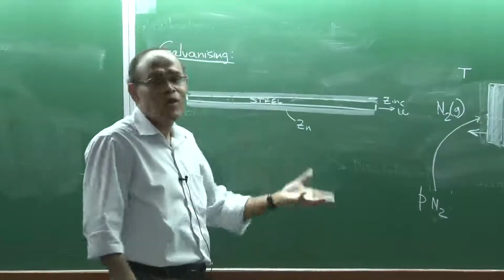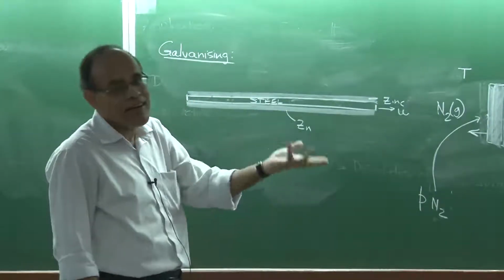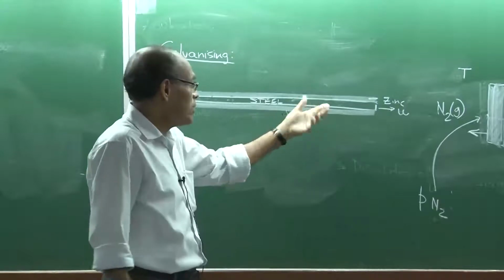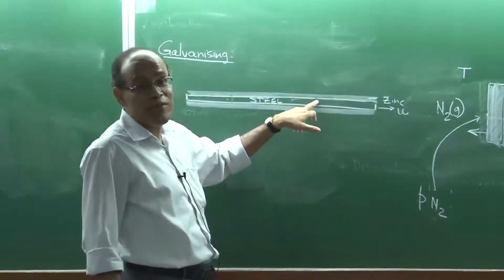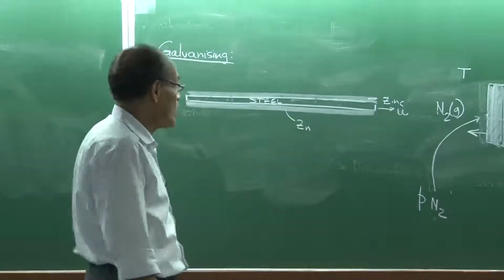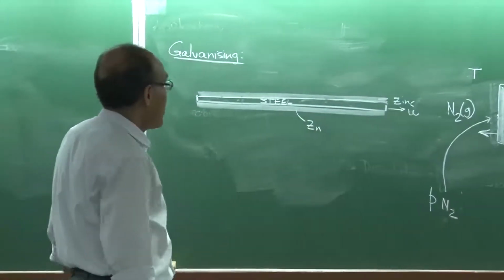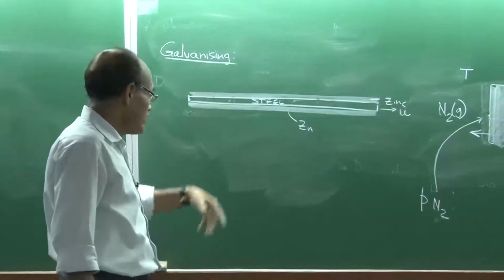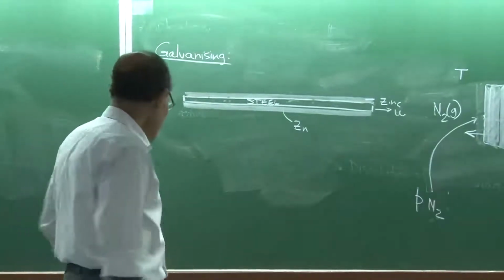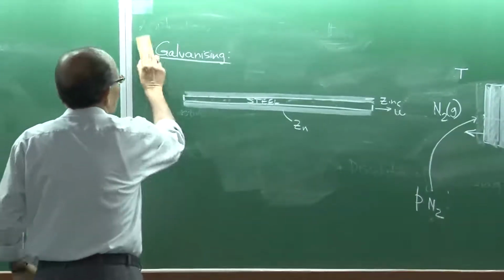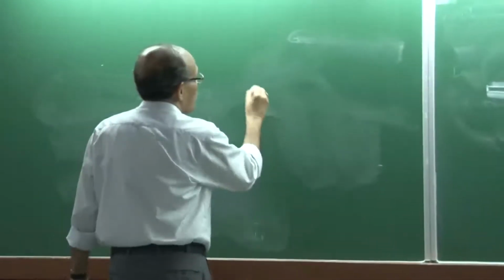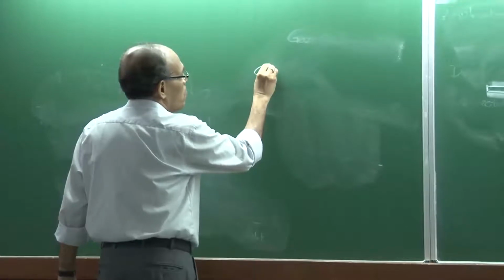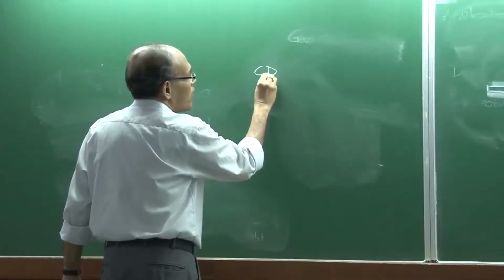Based on Fick's second law, in cylindrical coordinates, Cartesian coordinates, whatever it may take, you should be able to find out to what extent zinc has penetrated and what are the various kinds of intermetallic products that have formed. If you look at, for example, a two-component system with diffusion and chemical reaction, the equation can be written something like this.